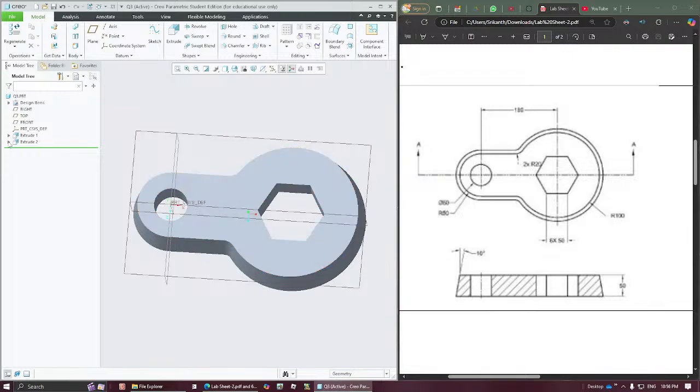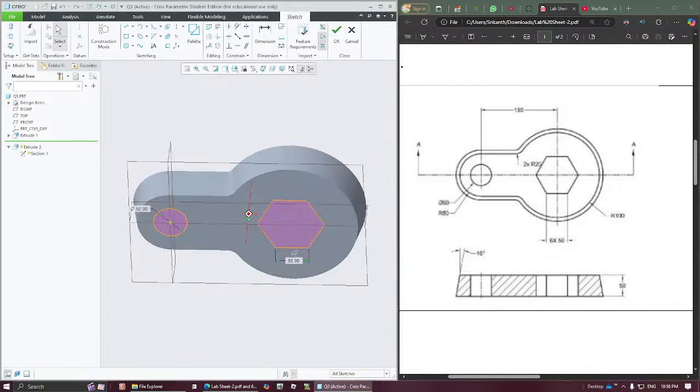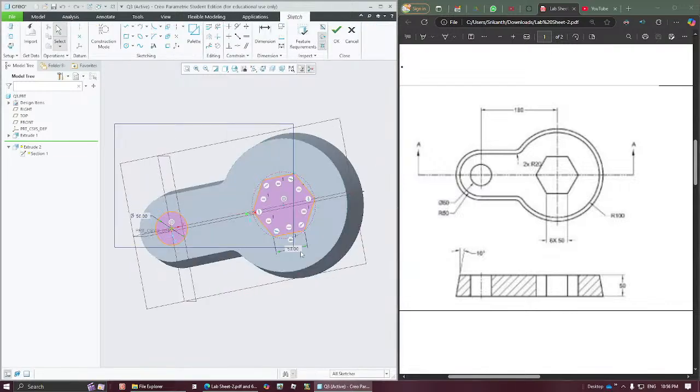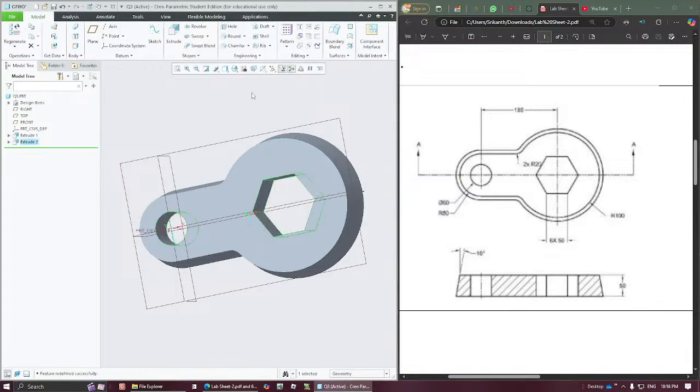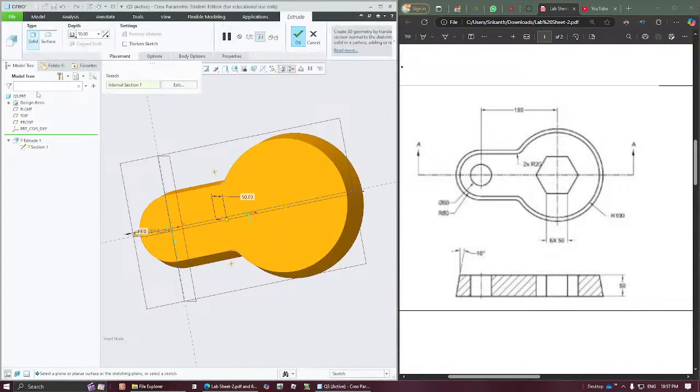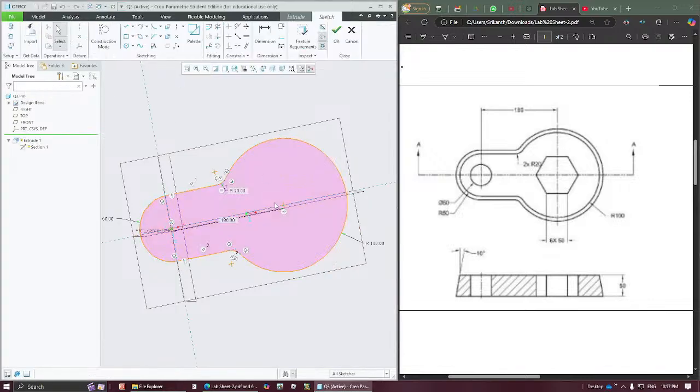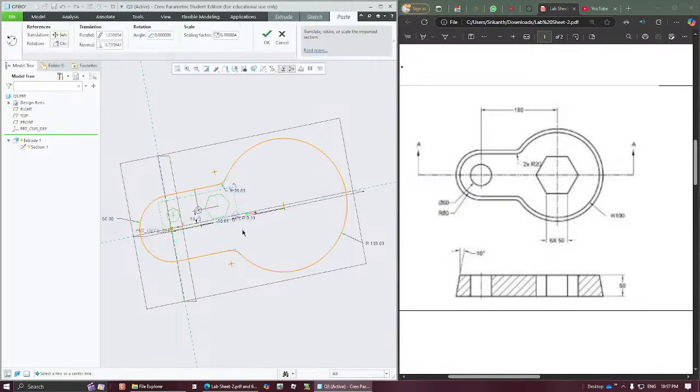Now, what would have happened if we had created this set of objects in the upper sketch itself? Let us check that. So I'll select them, copy, and I'll come out of this sketch. I'll go back to the previous step wherein I have created only this extrude, and then I'll go ahead and edit this, go to its sketch, edit, paste these objects over here.